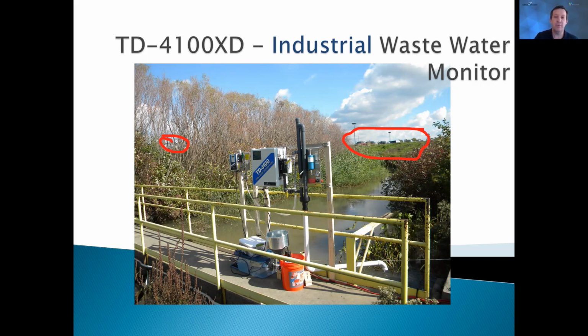The primary feature is this piping assembly right here. The water comes out of the piping assembly, runs through this little tube and back down into the flow cell. Once it reaches the flow cell, it falls freely through with no contact to the optical surfaces. Without any contact, the device doesn't get dirty. So operating in a process like this dirty water, we measured between 10 and 30 parts per million of oil for 30 days without it needing to be cleaned at all.